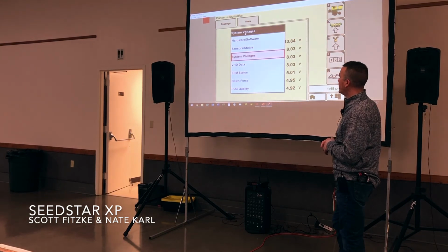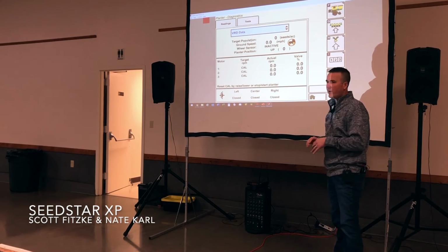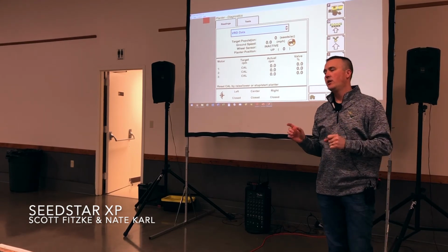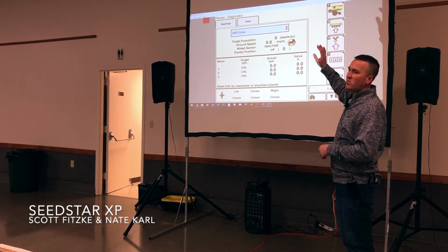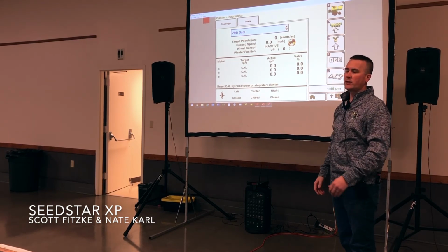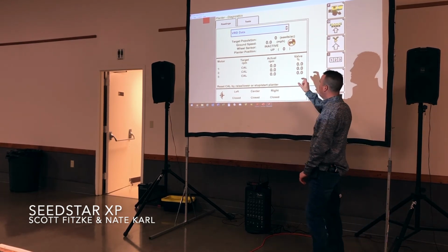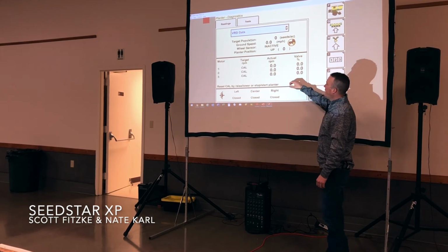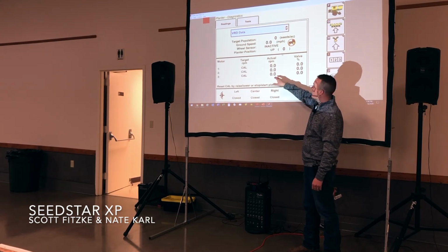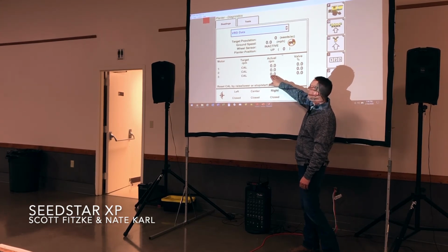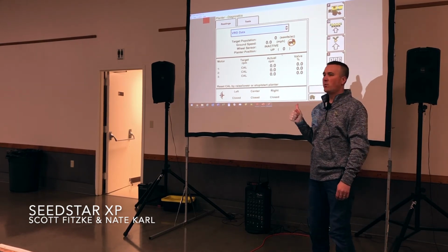There's our supply voltages. Regular rate drives. This is a good idea if we've got multiple drive sections on a planter. Let's say we were watching our main run page and noticed that maybe that right wing is dragging down a little bit, or it's consistently high or consistently low. We can come in here and dive in a little bit deeper. If I've got one of my motors dragging, as we talked about on a wing, and its RPM is significantly less than the rest, right there I know that's why my population is low.